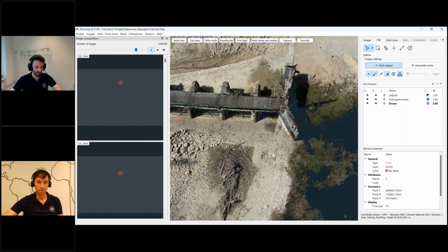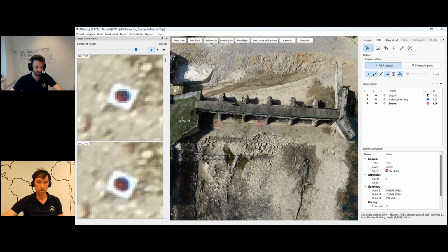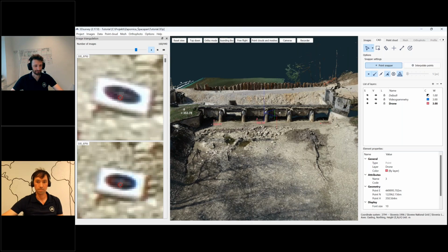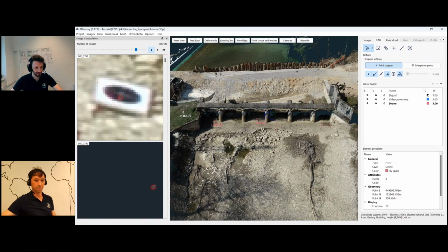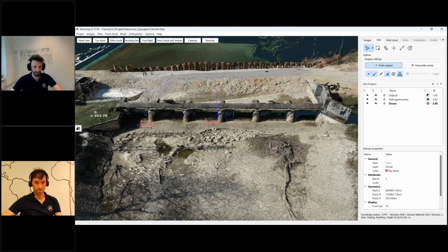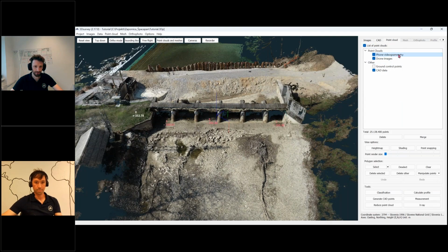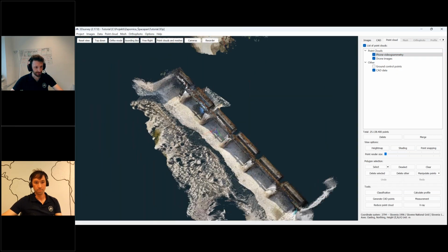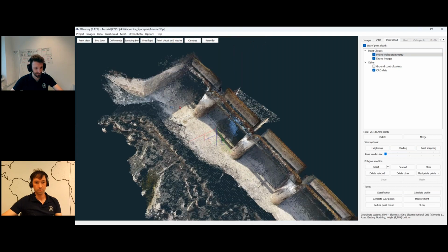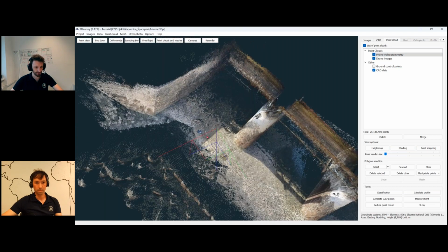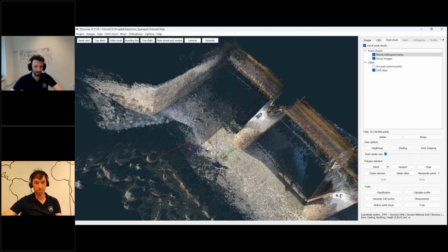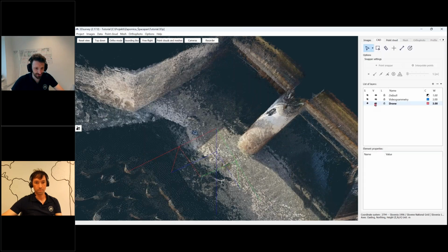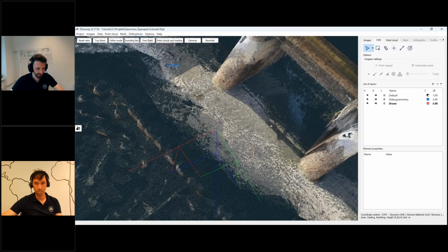And I've done my drone point cloud now. For the second point cloud, you need a second CAD layer. First, zoom to your second point cloud, and now repeat the process here. You make a new CAD layer and go through these targets again. Well, I have already done that, so I'll just turn on this layer. Hope you don't call me cheating for this one.